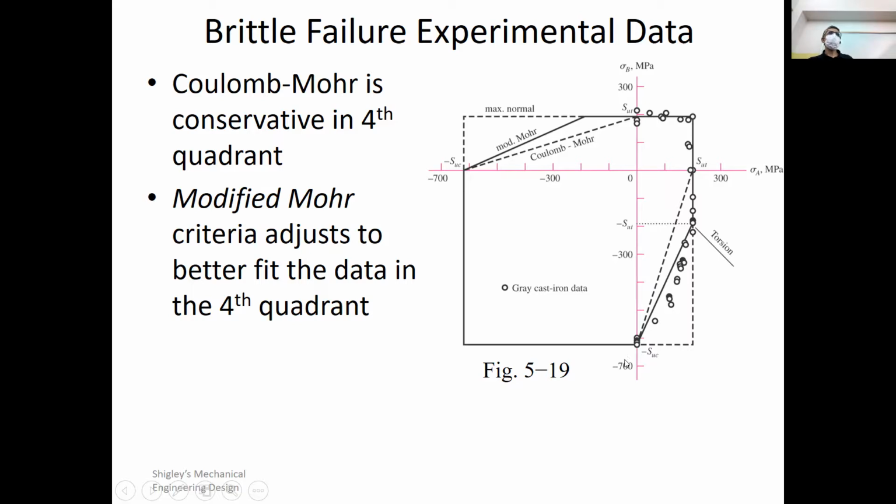Now, using equations, you're going to end up having 4 scenarios. So yes, you can use the equation to find a design factor. But again, like Mohr's circle, these failure envelopes, graphical methods, for us engineers are great tools because they help us answer the what-if questions. So I always encourage you to use these envelopes in addition to Mohr's circle.